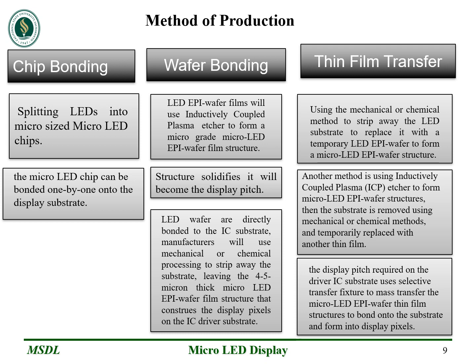To fabricate a display, first, a micro LED wafer must be created by high-yield epitaxial growth. Then each individual unit must be transferred to a substrate or backplane that holds an array of units in place. The transfer equipment used to place micro LED units on a substrate needs a high degree of precision, with a placement accuracy within plus or minus 1.5 micrometers.